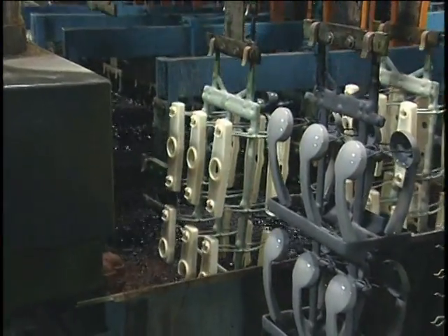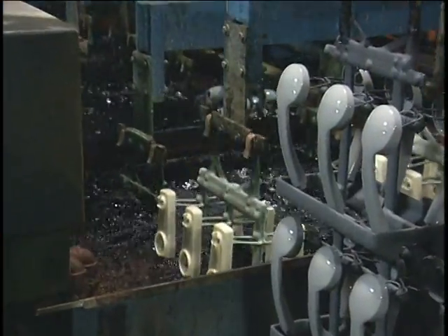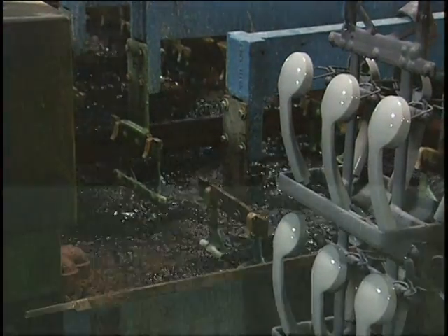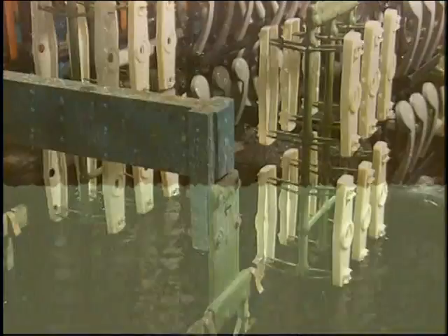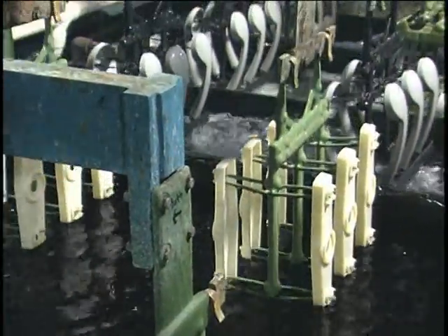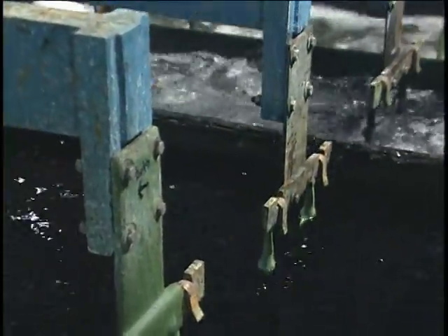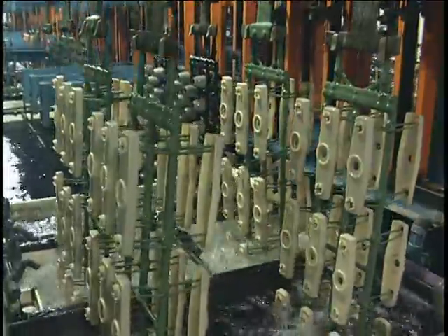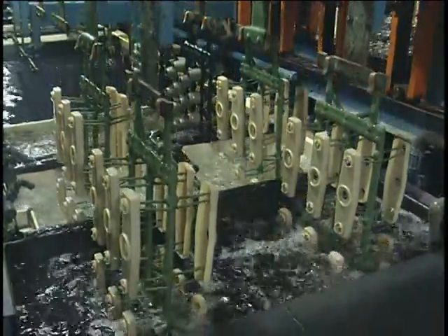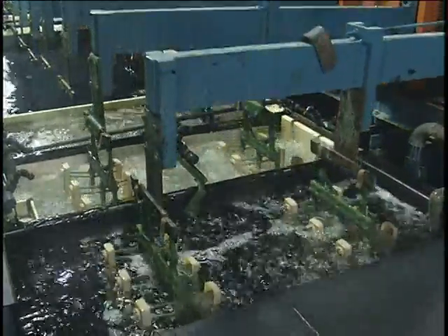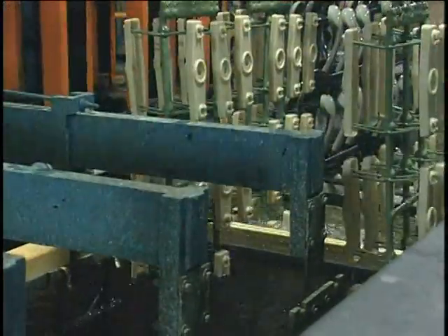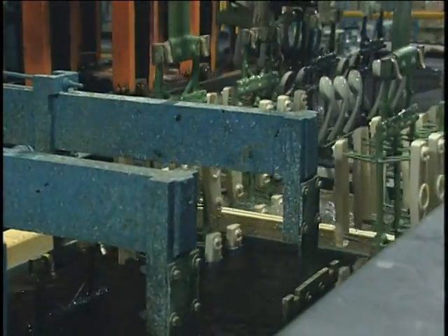electroless plating by submersion in a sulfuric chromic acid bath. This acid slightly etches the plastic substrate surface, creating microscopic pockets or pockmarks. After etching, the plastic parts are placed in an activator bath and an accelerator bath. These baths line the pockmarks of the part surface, making it chemically attractive to the metal suspended in the electrolysis